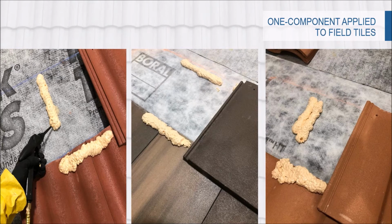You can see here, these are the three profiles of tile, but notice the beads, they're a little bit different as far as what system you're using. On the left there, that's that medium profile of tile, and you see a horizontal bead on that headlap of the tile and a vertical bead right on that underlayment. Once you get to the flat tile, you have two horizontal beads, and that high barrel, that S tile, is going to require a little bit more adhesive, and that's predominantly because of the shape of that tile. So again, it's important to get with the manufacturer of the adhesive product that you are using, because they have specifications that have been tested accordingly with their products.